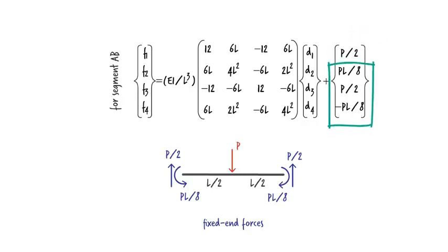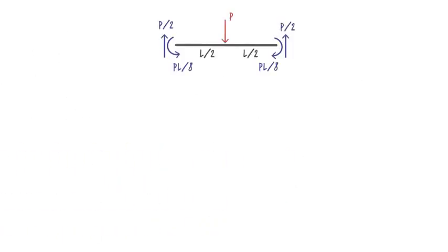Note that this bending moment is shown with a negative sign, since, according to our sign convention, clockwise direction is considered negative. We now need to transfer these fixed end forces to the adjacent joints and treat them as equivalent joint loads for P. To do this, we simply reverse the direction of each force and place it at its nearest joint, like this.